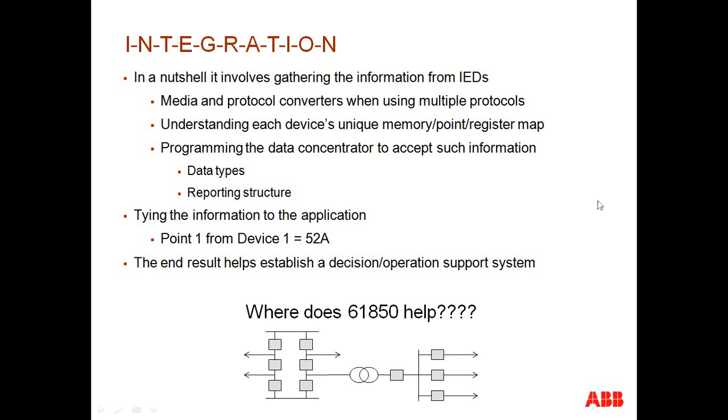When looking at some of those issues, integration essentially involves gathering all information from the IEDs, and understanding the media or protocol converters that may be needed, in the case that you have devices that do not talk a particular protocol, then you will need to perform protocol conversion. Integration requires a thorough understanding of the memory pointer register map of each one of the devices that you want to integrate into the system.